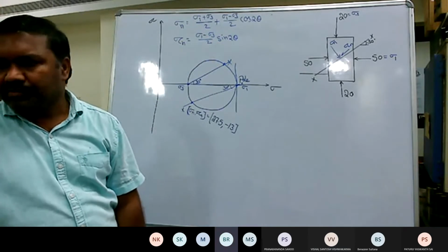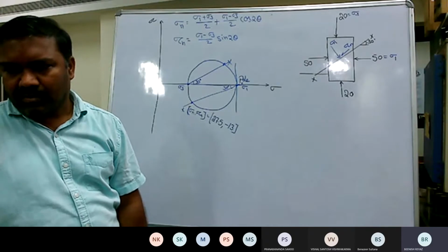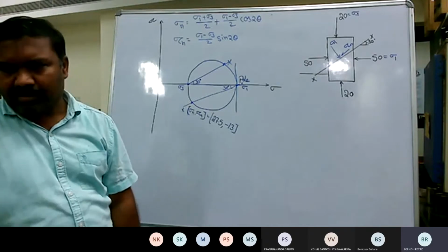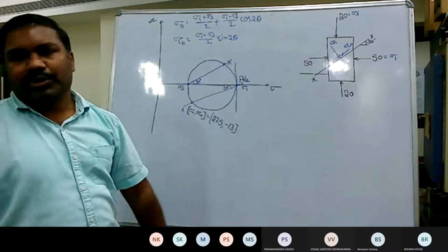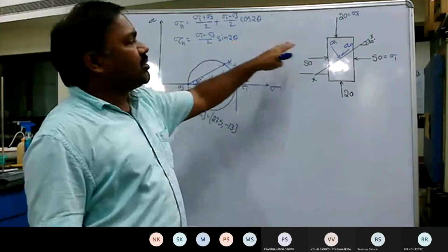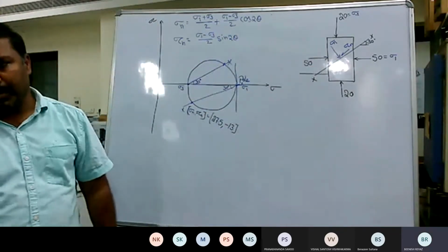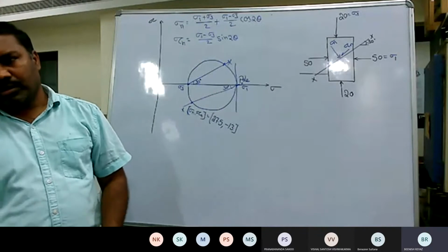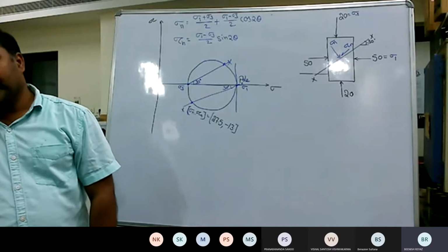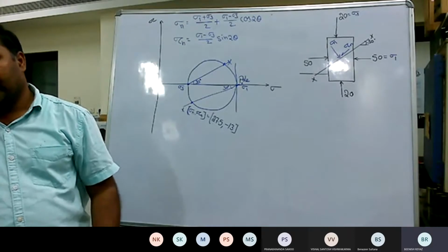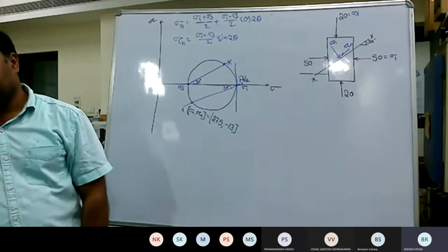So when we use the analytical formula for this tau, we get a positive value like 13. But from the graphical method, we get minus 13. Yeah, graphical is correct. You are getting positive because you are taking theta with respect to the minor principal axis. The moment you take it with respect to the major principal axis... No, sir, I took theta as 60, that is with the major principal plane. Sin 120, sir, you take sin 120. Yes, sir.